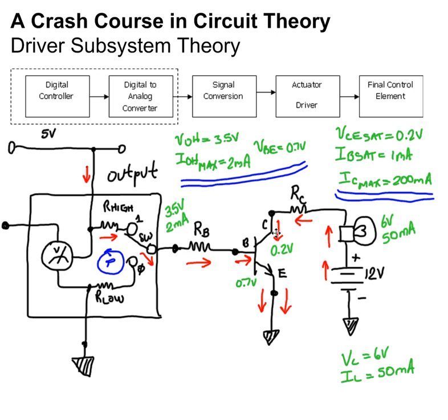In order to complete the design, we need to know what is the voltage required by the transistor when it's in saturation. From the data sheet, we see that it only needs 0.2 volts to operate, which means the other 5.8 volts will be across the collector resistor.